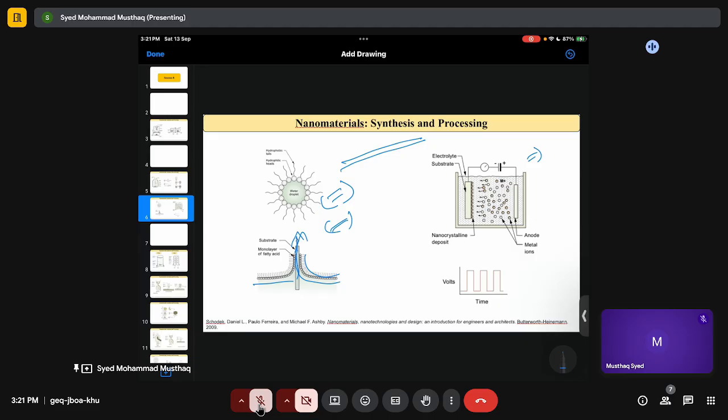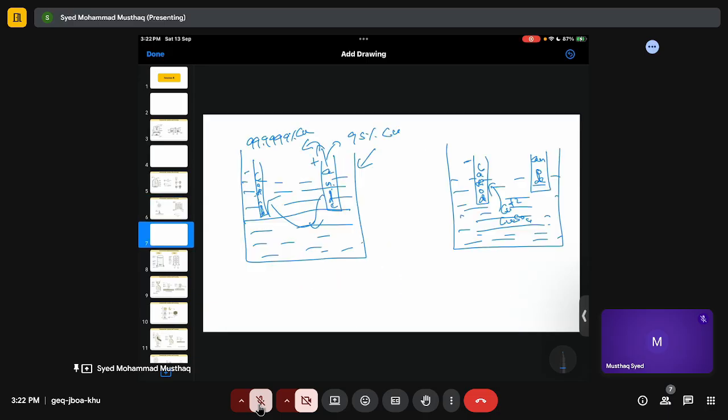And yeah, here in electrodeposition, this is simple deposition where you take elements from the anode and you deposit on the cathode. Now once you try to do the deposition, what happens is, once we start the deposition, at first some places you will have deposition, and some places it may not. So what happens is, we are continuously supplying electricity, right? So instead of forming here, this guy grows, right? So you will have this columnar type structure.